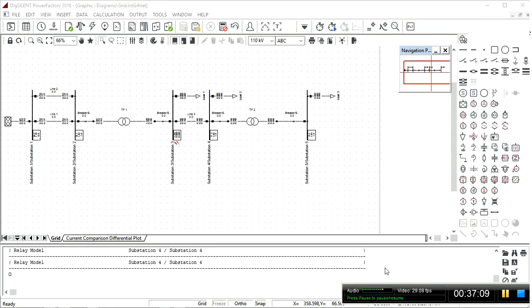So you can go ahead and try to set up differential protection for that transformer, and also conduct different faults at different locations of the network, and then you see how the relay behaves. And ladies and gentlemen, that concludes today's exercise on transformer differential protection. Thank you very much.